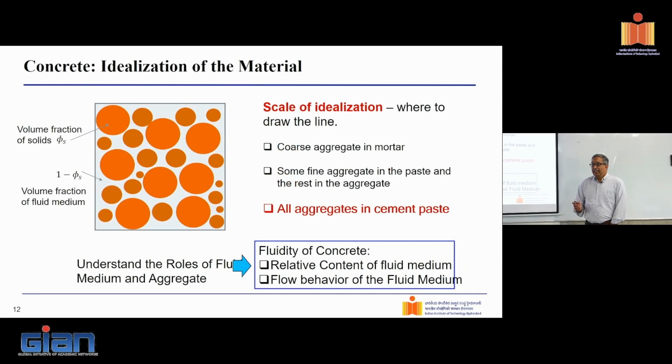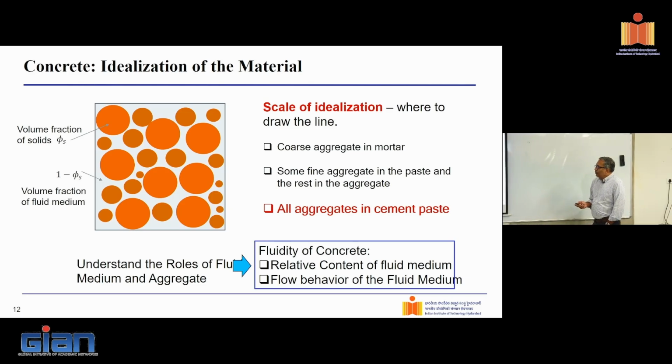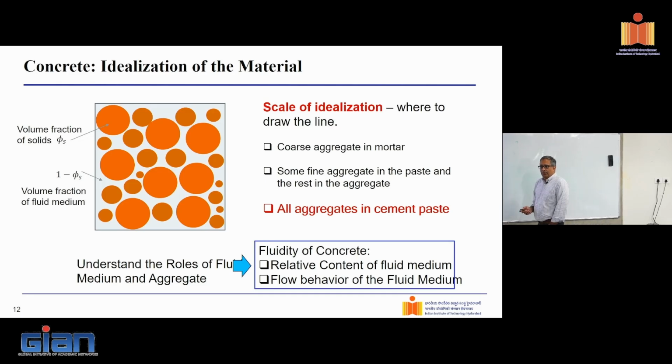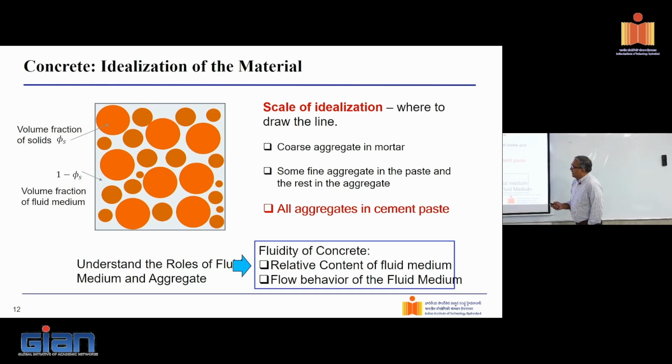Why is that important? If I have to get this fellow to flow, the rheology of the fluid medium becomes important. That means if I'm looking at that scale of idealization, I should have the fluid behavior of mortar in my hands. The second level I can also think of is where some of the coarse aggregate or some of the fine aggregate that we use become a part of the gray fluid, and some of the fine aggregate are considered as a part of the orange dots, the aggregate.